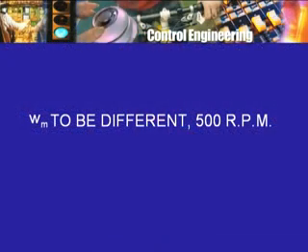Similarly, for the frictional coefficient Kf and the armature resistance Ra, it can be a change in parameter value, that is, under actual operating conditions something happens, and therefore Ra under actual operating conditions is not what it was when it was measured perhaps. But there is also the other fact that no parameter value is known exactly. Any physical measurement has always associated with it, besides inaccuracy, also precision. The best of instruments will have limited precision. It could measure within 1 millimeter or it could measure within 1 micrometer, but that would be about all. So either change in the parameter value or lack of exact knowledge about the parameter value, both of these effects can be thought of as causing omega m to be different from the design value.